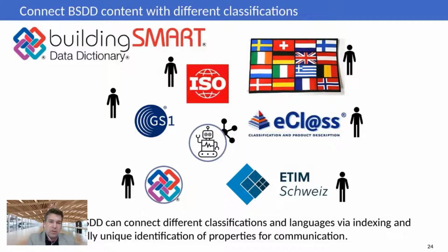First, I always thought we have to define, first of all, IFC property sets and IFC entities, and now I switched more to this machine readable level, which can be then connected with classifications if needed. So it's then really up to the CAD program companies to decide if they really want to have these properties in IFC, or if they just rely on BSDD, and so it is with all the other classifications.